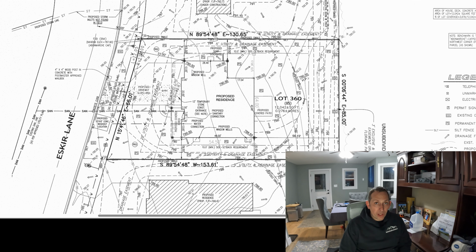So what we're showing you here is a site plan that also shows the corner stakes for the foundation. What that means is they already went out and drove 4 stakes in the ground to reference a square, right? Because your excavators have to know where the house is on the property. And if you just give them a site plan with no marks, no stakes in the ground, absolutely nothing, their life's going to be pretty hard. So we send the engineers out and they drive 4 stakes in the ground, and they are these little boxes right here, right here, right here, and right here. And what you'll see is they create a rectangle.